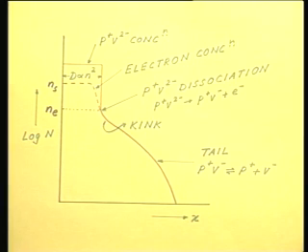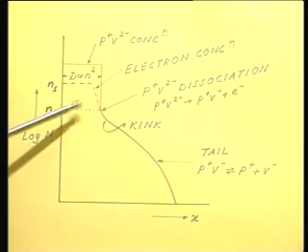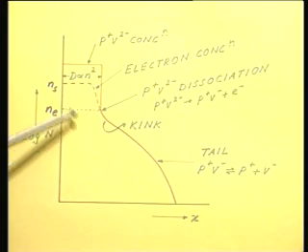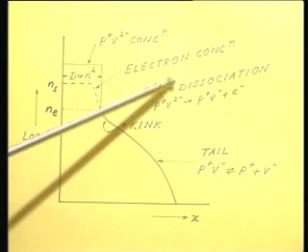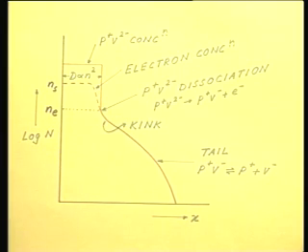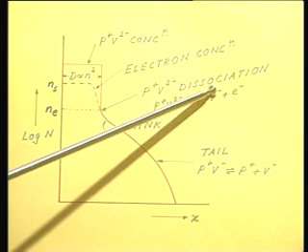So, in the phosphorus doping profile you will see that in the different regions different terms dominate. Closer to the surface, where the doping concentration is very high, the diffusion coefficient is proportional to n squared. Then as it falls below a critical level Ne, at which the Fermi level is 0.11 electron volt below the conduction band, at that point this P+V2- dissociates, giving rise to P+V-.